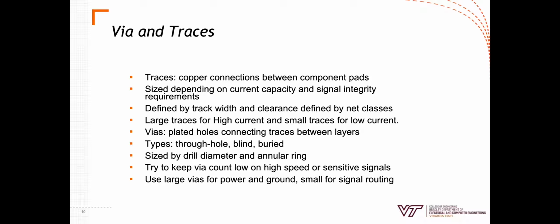So if you've got a power trace that needs to supply power to multiple ICs, then you're going to want a larger trace. If you just have a small signal trace that is carrying a very low current signal, maybe we're talking about a USB connection, then it can be very small, and you want to just make sure that it's small enough to actually fit onto the pad if the spacing is really tight for your pitch. And I'm going to give you a bunch of predefined track widths so that you can utilize them when you're actually laying out your PCB. They're pretty handy.